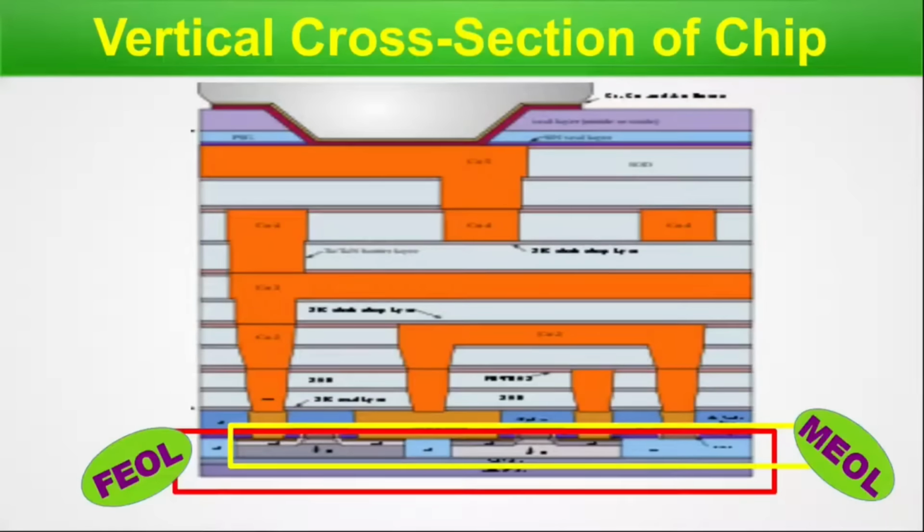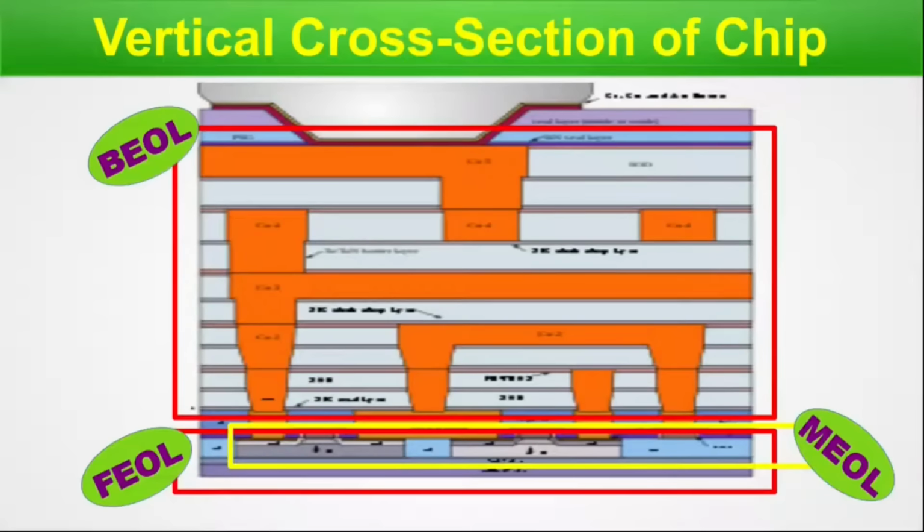Next, the transistor level or the active or passive level device interconnections are done through the MEOL process. So this is a very low level connection. You can see we have not used any vias or higher metal layers. So it's very minimalistic interconnect. And the rest of the interconnect, whatever we do in the PNR level, in the SoC design, or specifically in the physical design process of the SoC design, all those interconnects, that is the metal and via layers, are fabricated through the BEOL process. So this explains what are the things. So front end of line, then mid end of the line, and then back end. So this explains the three processes: FEOL, MEOL and BEOL. We are done with this particular slide, so let's move on.